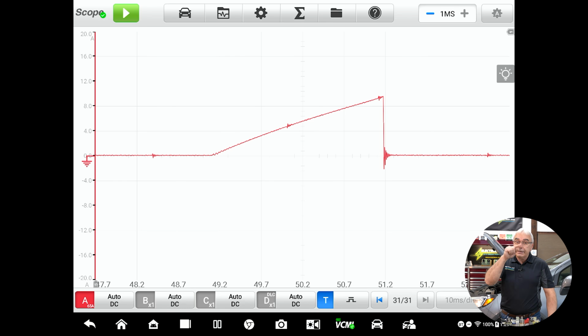So I should see those up and down little hash marks where I first turn on and ask this thing to start doing a job. If I don't see that, if I see a sharp uprise and then the slope, that's a pretty good indication that you've got a shorted ignition coil.